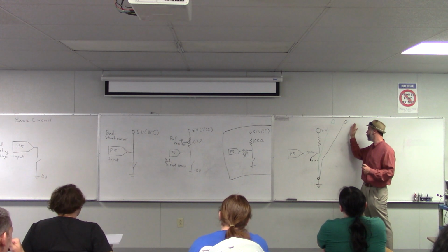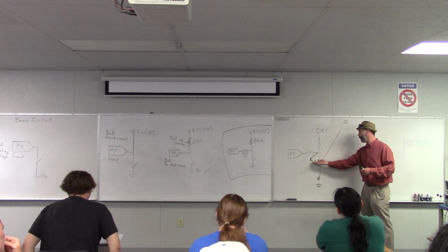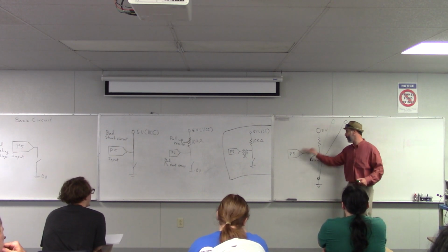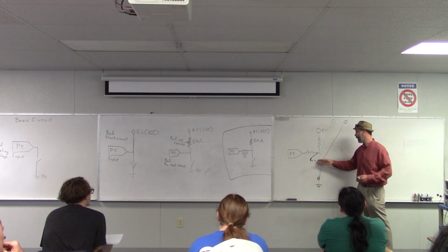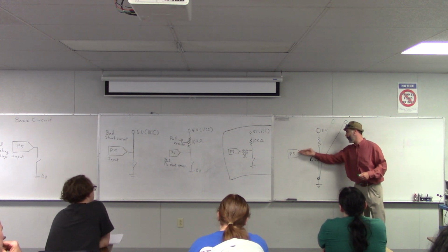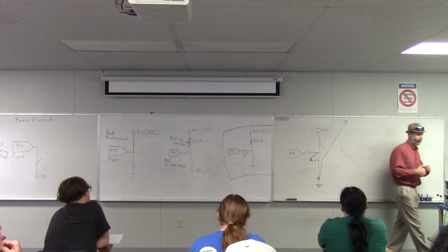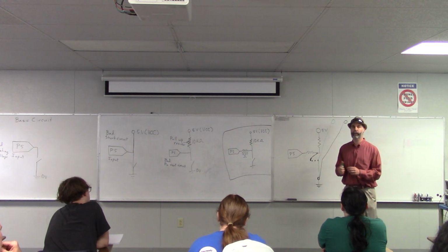So that's how the Whisker acts like a switch. When you're driving along, it's away from these pins, this header, and your pin voltage is high. When you bump into something, the Whisker gets pushed back, it closes the circuit, pulls that voltage down to ground, and you get a low voltage. Okay? So that's how the circuit works for the Whiskers.